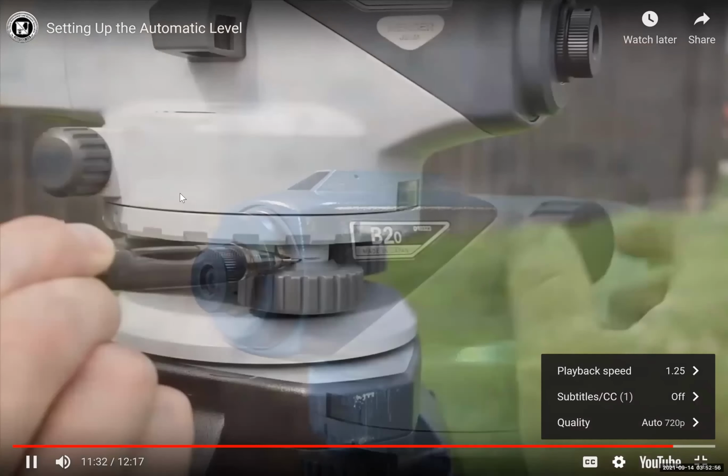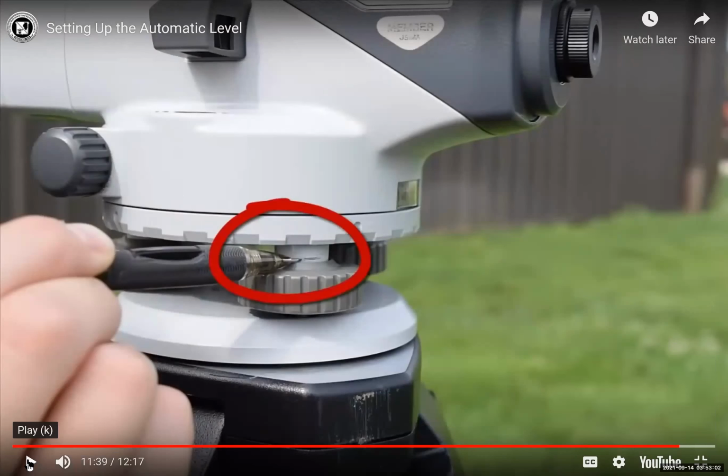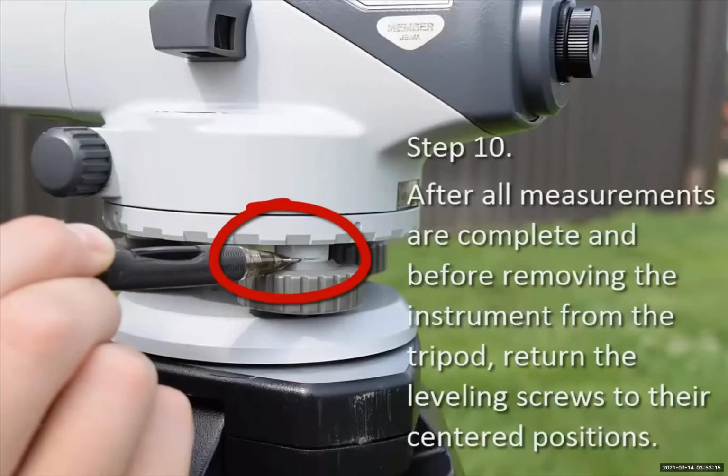The mark you see here above the leveling screw indicates the center of the adjustment range. If you don't check for parallax, that's another reason that you might have a surveying error. After all measurements are complete, and before removing the instrument from the tripod, return the leveling screws to their centered positions. The next time you remove the instrument from the case, the screws will be centered and ready to use.